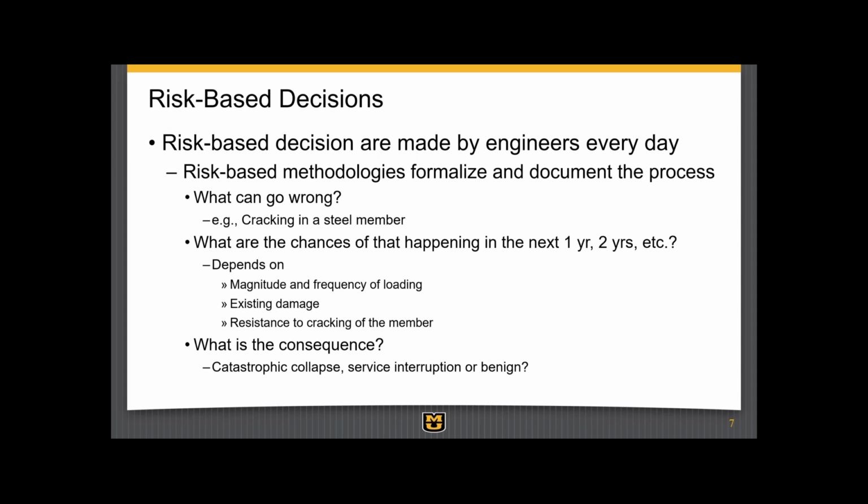That could depend on things like the loading that the structure's experiencing, if it has existing damage, or if it's got resistance to a particular damage mode that you're talking about, like cracking. And putting that together with the consequence of the damage. What's going to happen if that damage were to occur?